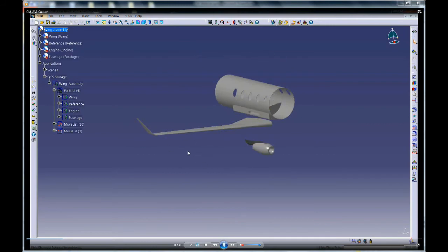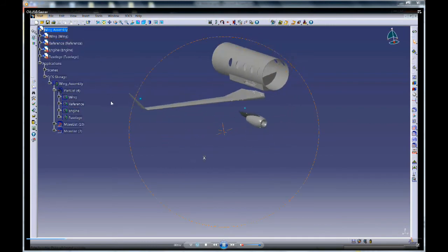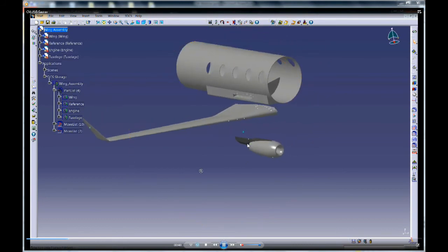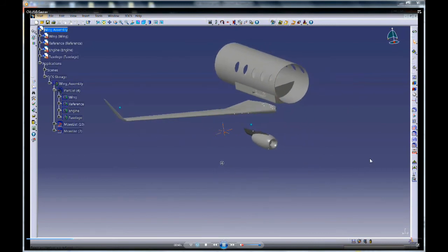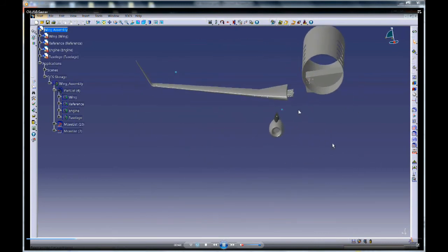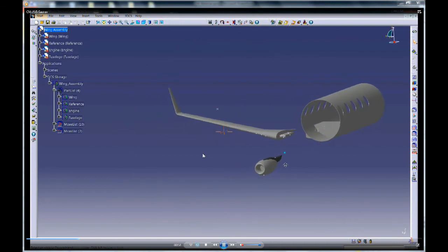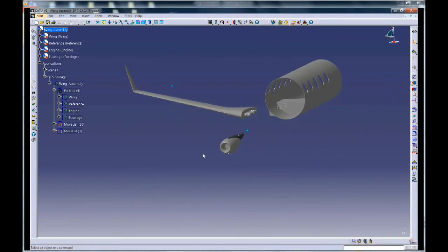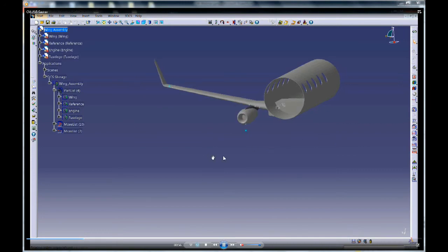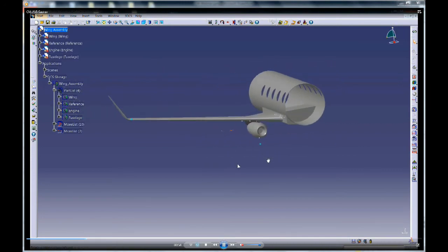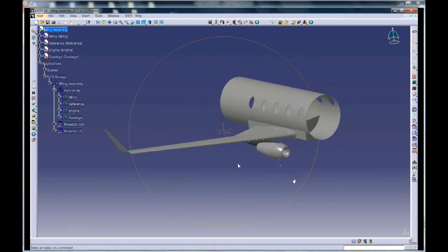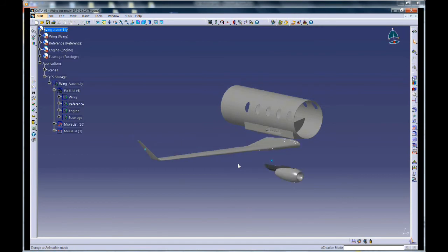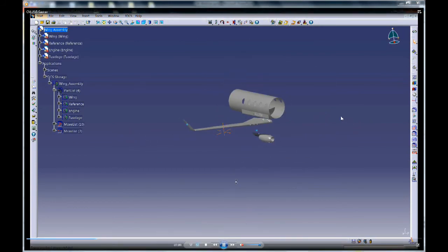Just to make the model simple, we just created wing as one part instead of assembly. So this shows all the points which were used for the DCS model. These include all the tolerance points, measurement points, and move points. If I do a nominal build, that builds the assembly by running all the moves. Yeah, this is the separated position.